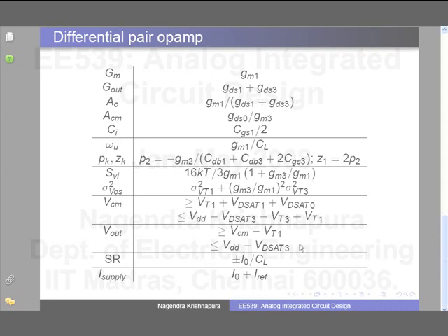Okay. So if you just increase the current in the op-amp, the unity gain frequency no doubt increases, but the swing limit will reduce. Okay. And the power dissipation increases directly. So let's do the other thing. Let's increase the size. What happens then?